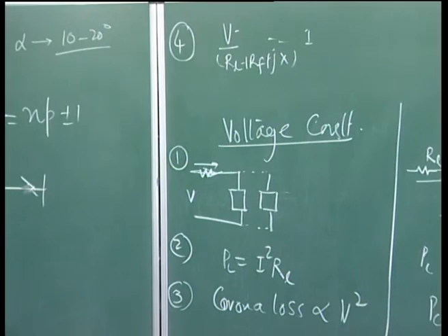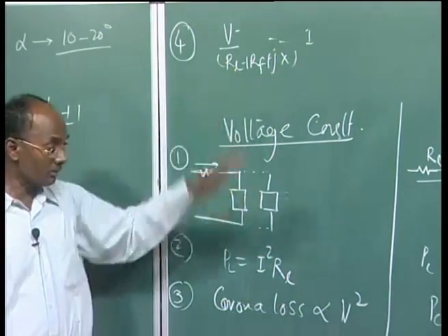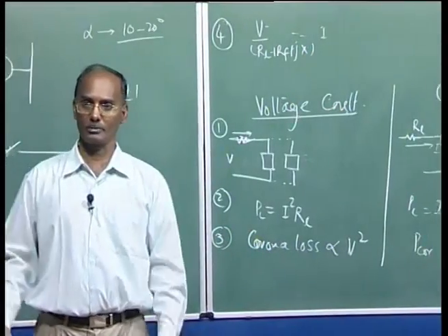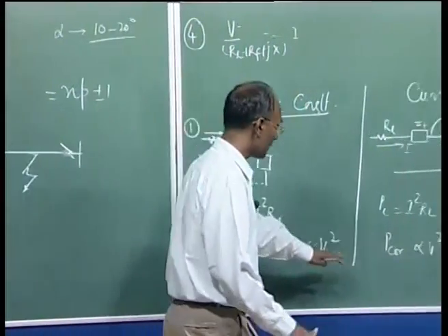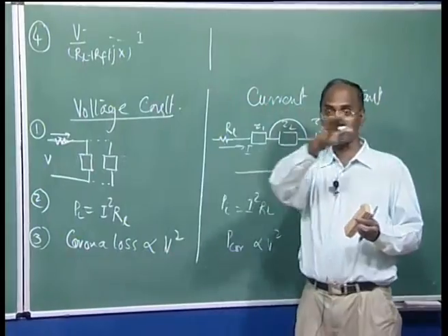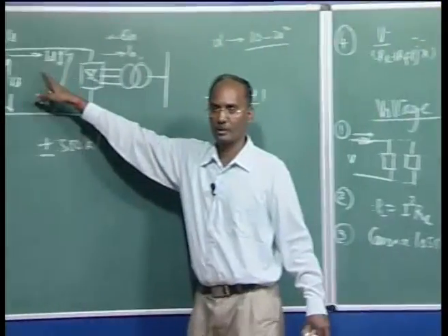This is normally 5 to 6 times, depending upon what the RF value is, etc. But what happens, you have the circuit breaker, it will be automatically tripped. But if you are up here in the constant current mode, your current cannot exceed that value, the rated current. So even though there is a fault, the current here will be the ID.